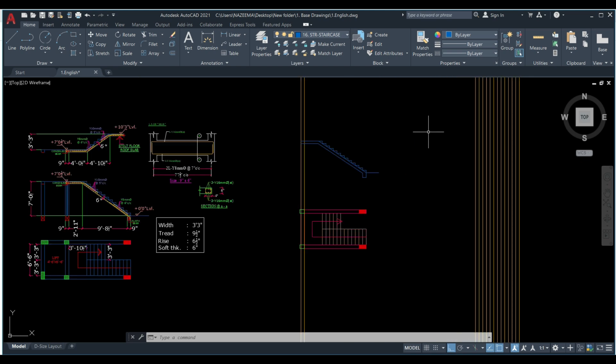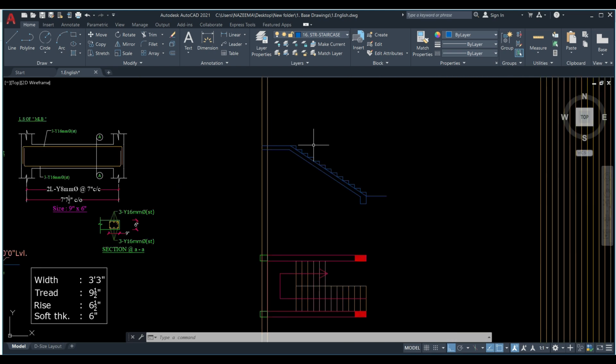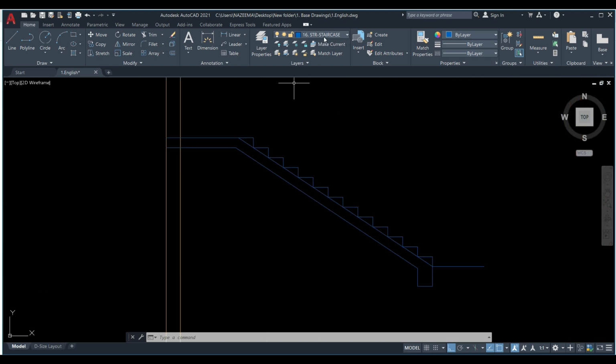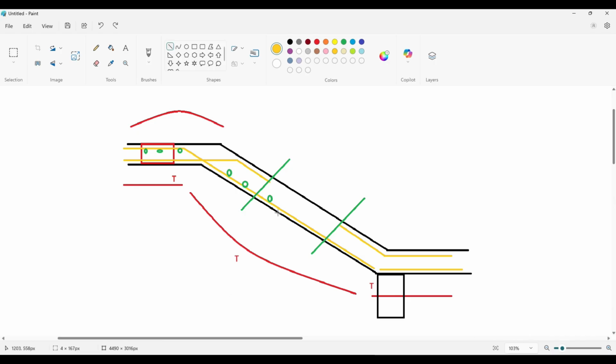All right, so coming back over here, I have kept all these lines separately. We can delete them later if you want. So once that is done, I'll come to my structural cases and make this current. Now, once my shape is done, we have to start drawing the rebars. If you remember the earlier part, what did I say? Whatever reinforcement is there, it goes and connects to the top, right? So let me first draw that particular rebar.